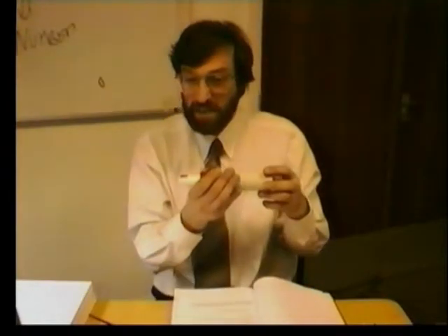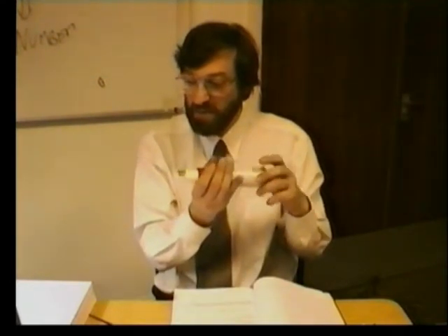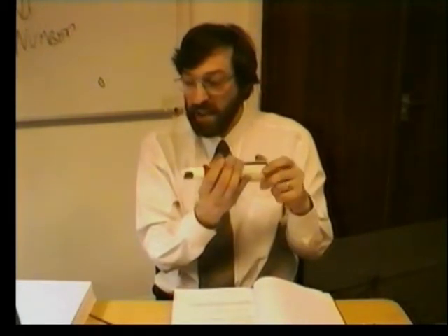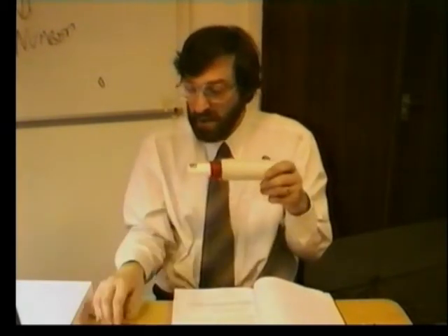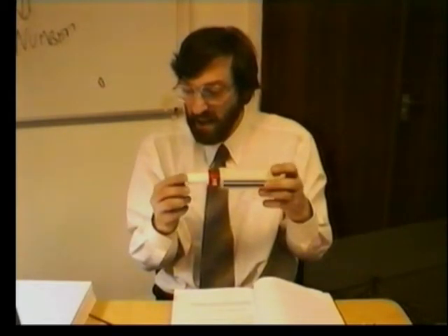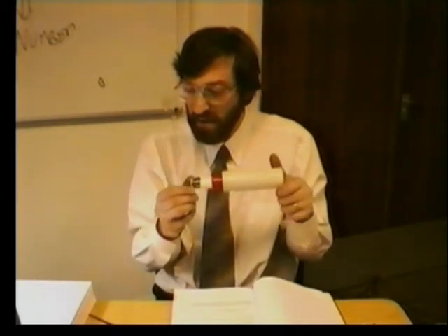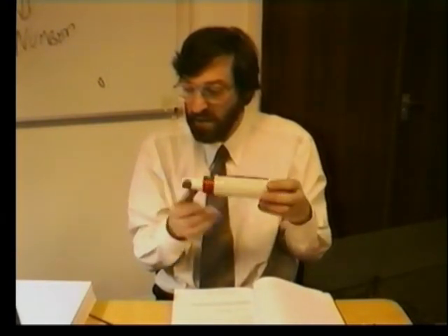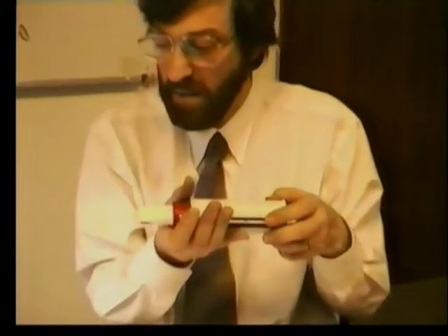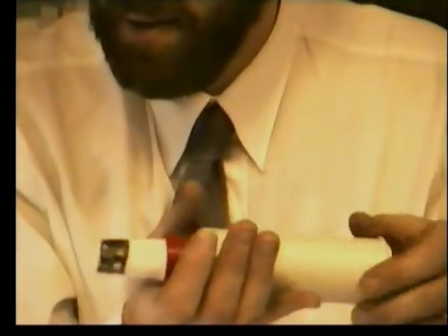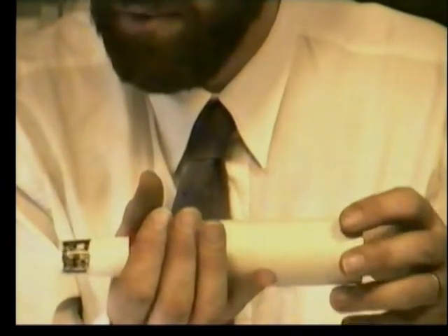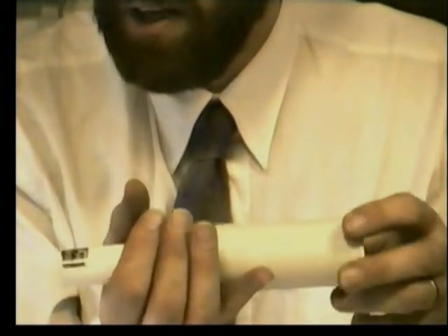I'm going to use it as a pretend shaft. Let's assume this is a shaft in a piece of machinery, and it's rotating round and round. How do I know how often it has rotated? Well, you might have noticed at this end of it I've put in a little black mark. So there we have black, white, black, white. Now, every time it rotates, if we count the number of pulses, the number of transitions, we know how often we've turned.